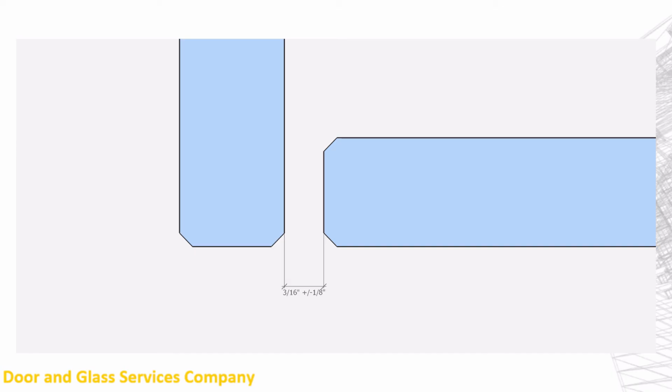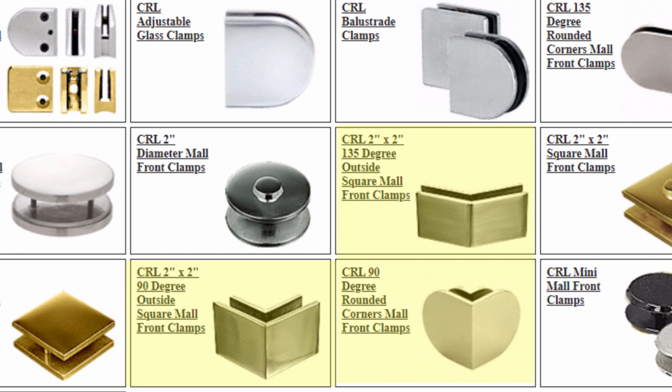Now, as you know, there can only be a finite number of different ways of creating these corner joints. An option is for us to have nothing between the panels, only air. When we elect to use that option, we're going to deduct 3/16 of an inch. We can also use mechanical clamps at the corner condition to fix the panels to each other. The clamps can, like inline joints, have a fastener or they can rely on adhesives to hold the dimensions of that joint fixed.